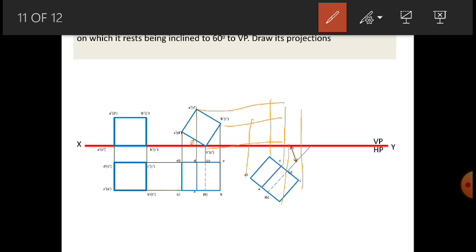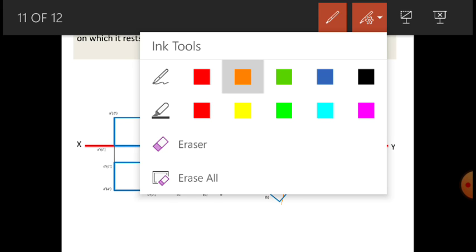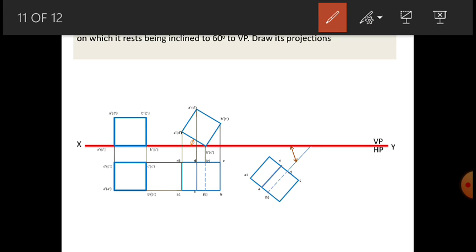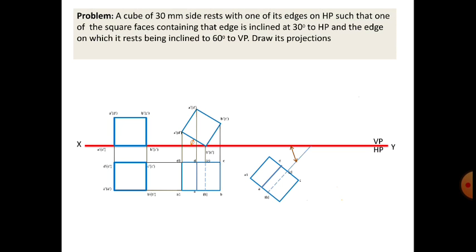Once you get these projected lines, see the labeling done on both the objects and intersect those points and mark them as A, depending upon the labelings. Like this you will get the projected lines from both sides and intersect at one point.